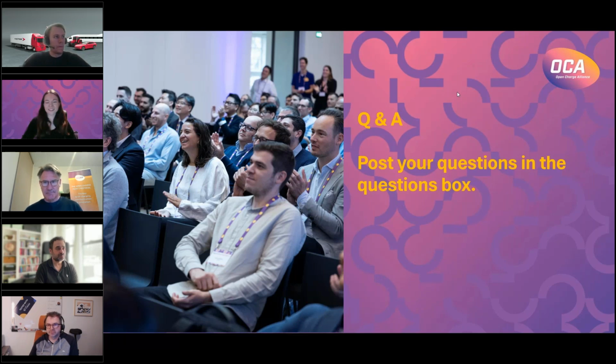All right. So let's have a look at the next question, which is about the receipt functionality. Can this functionality also be used if the payment terminal is integrated on CPO or OCPI level? Yes, I think this refers to when you have a standalone payment terminal, where you have, for example, a payment terminal booth for an entire charging plaza or a group of charging stations. And then usually this payment terminal communicates via OCPI with the CSMS. And that is indeed supported by our use cases.